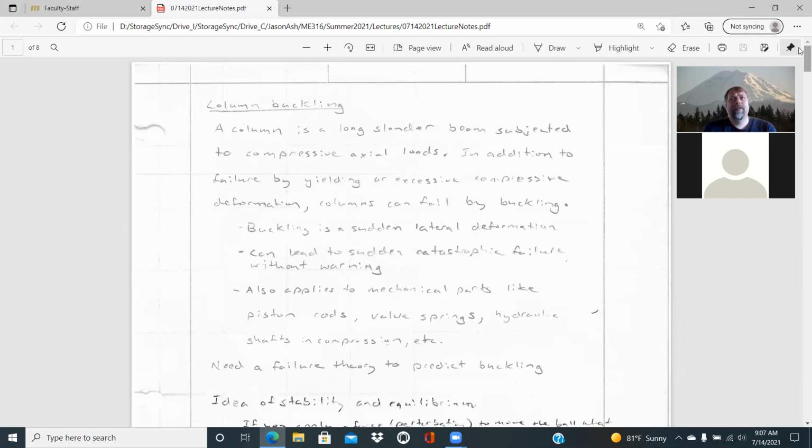You'll see that on aircraft too. If you look at the older aircraft, you'll see cables being used to support tensile loads, which would be experienced in, say, an aircraft wing. Then they'll use compression struts, solid metal sections, usually circular sections, that are able to withstand compression loading in those areas.